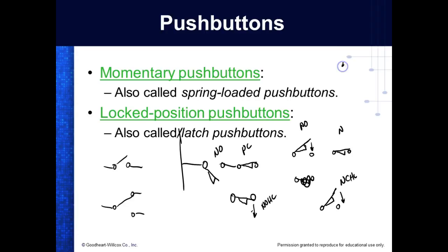If I came over here and did this, I'm going to come down here and do this, and then I'm going to put this little dashed line. It means they're mechanically connected. What is this? Double pole, single throw. Yeah, because each switch has only got one position. Okay, understand? Now, if I come over and did this, and this is pretty much, well, the limit, guys.